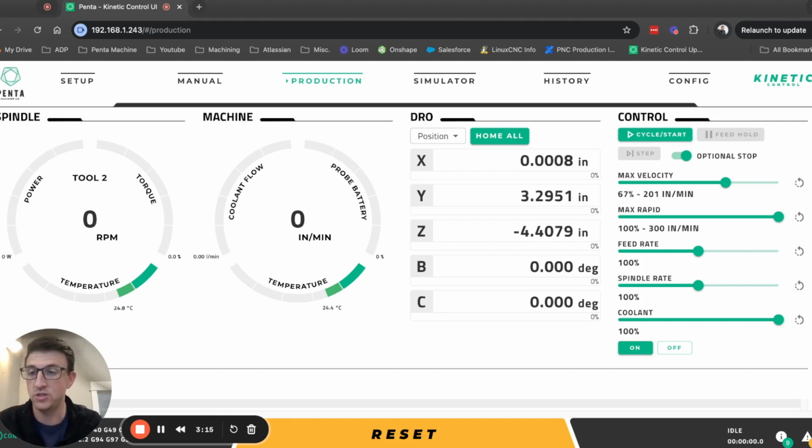Now, of course, as I mentioned earlier, this comes with some risks, so please be aware of those risks. You want to make sure that because you can't see the machine, you don't try to move it unless nobody's around, and you don't rely on this for quickly stopping a machine that is failing in some way. So keep those in mind, but this can be a very handy tool for checking on the machine, uploading G-code to the machine from your computer, say across the shop or something along those lines. It's very cool, very convenient function.